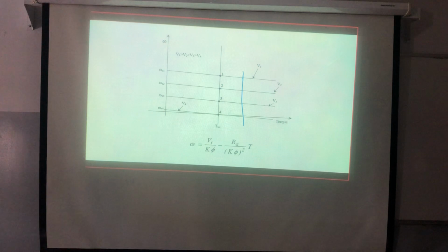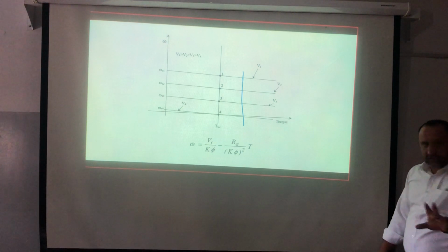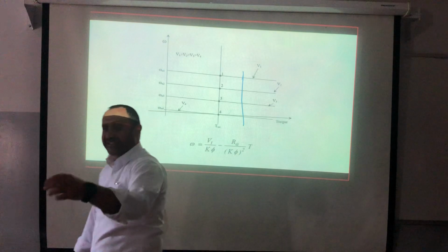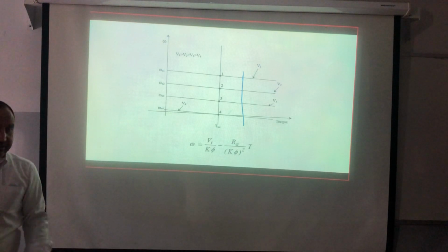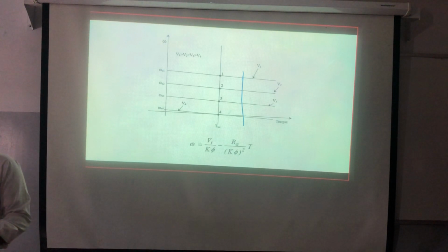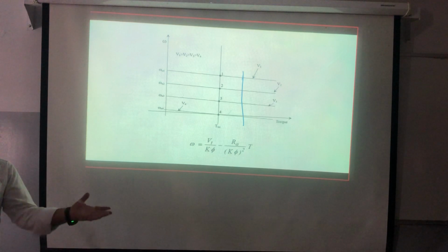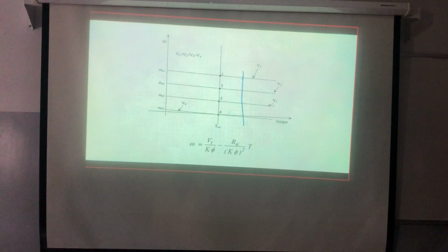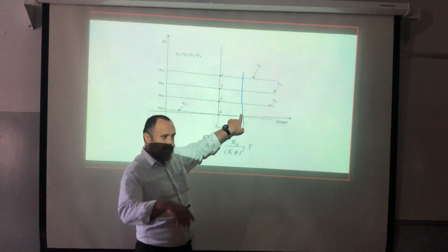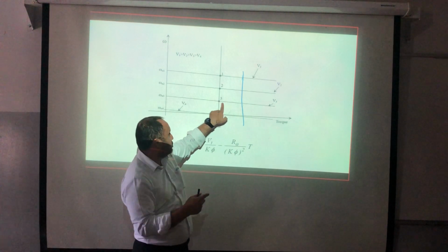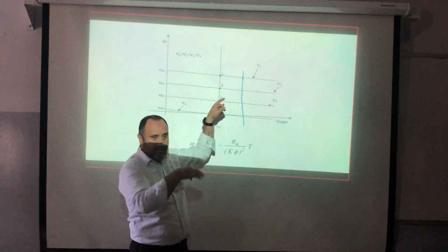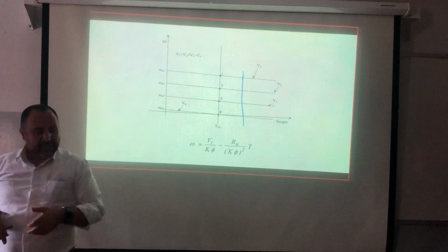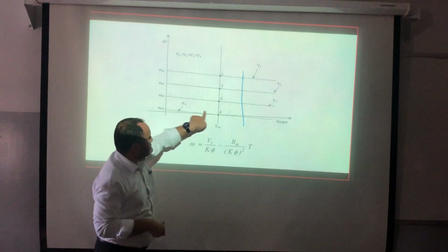I need to adjust the voltage and level such that the current is never allowed to exceed 3 times the rated. 2 times the rated. Who specified this? Twice the rated, 3 times, 4 times, 6 times the rated. Let's say the transient capability of the machine. Because here I will never operate for a long time. This one, yes, I will operate for a long time. Here, no, this is a transient, let's say. So let's assume that I'm forgetting line number 4.